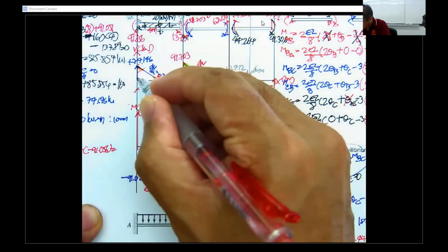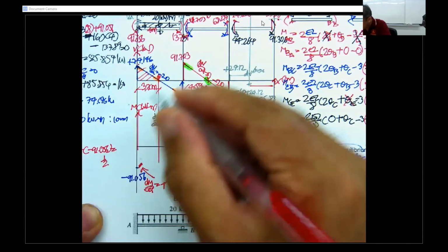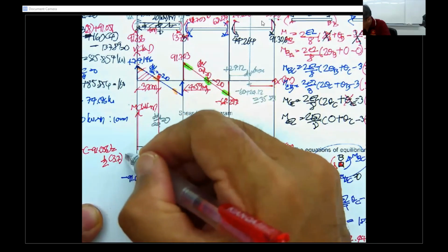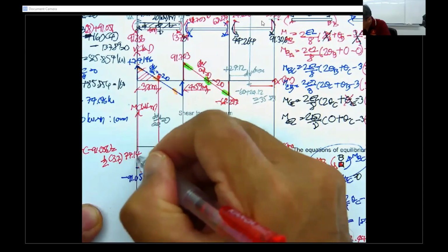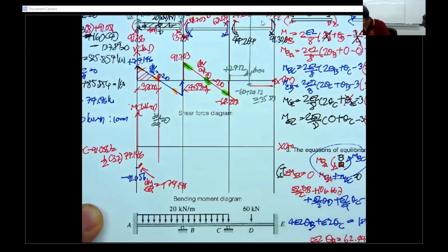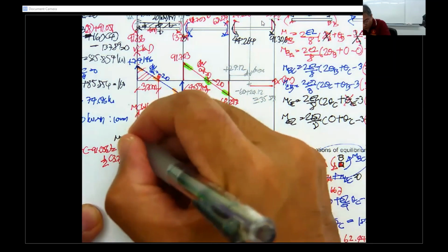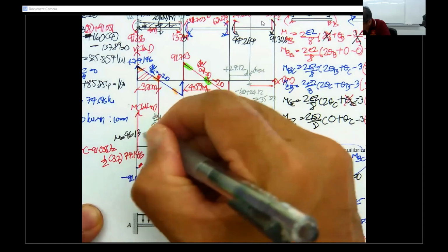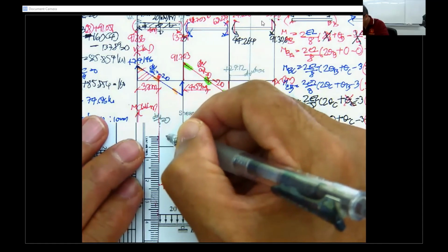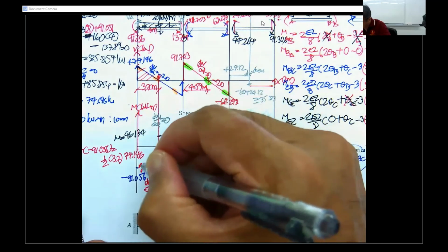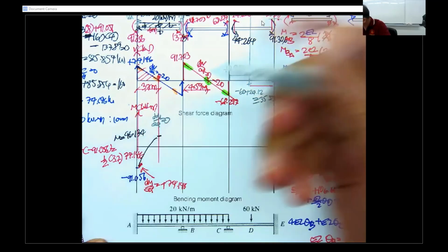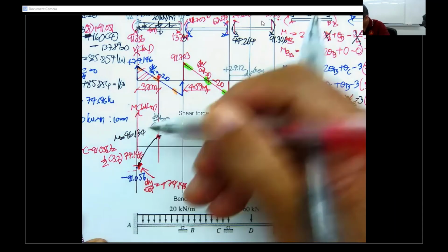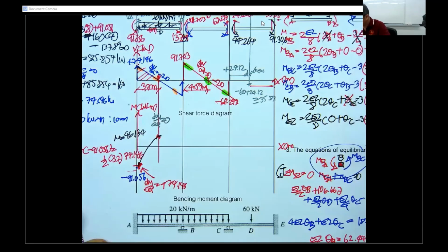And the moment over here, M over here, minus 91.056, is going to be equal to the area here, 1/2 of 3.7 times 74.146. Okay, if you push everything in your calculator, your M is going to be 46.134. So this is about 4 point something millimeter. So your curve is going to be something like this, and make sure this is going to be your correct slope.